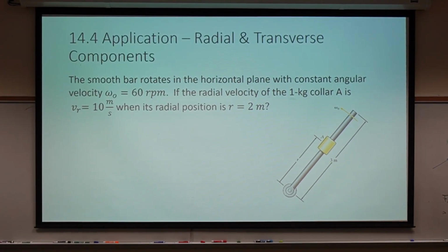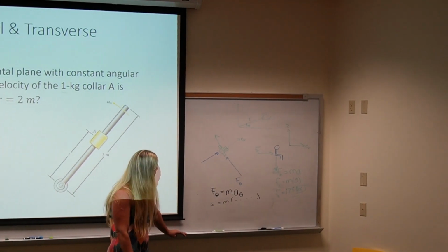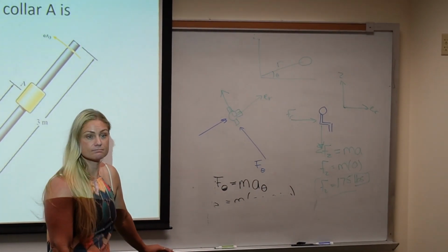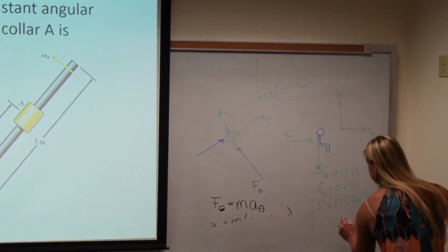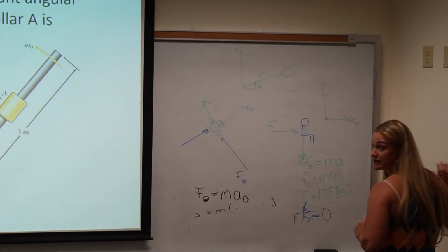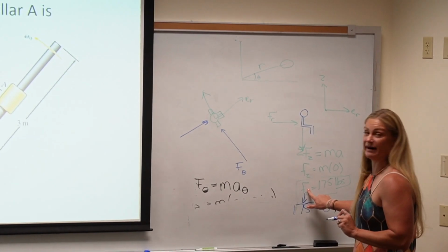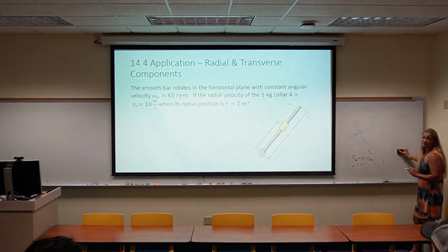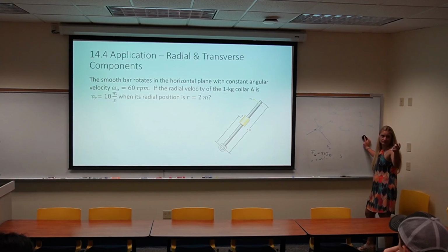Yes. Just really quick before you erase the vertical plane, you have sum of forces equals m times 0, and then the line beneath it you just have equals to 175. Is it just because it gave us a weight, which is a force? Yeah. Okay. Yeah, because I could have written it like this: 0 equals 175. So this just equals 175. Because this doesn't make much sense, right? Right. You just want to know what that value is. Yeah. Okay. That's okay. You can ask questions. I guarantee the questions you are asking, the same people at home are thinking. So just stop me and ask.